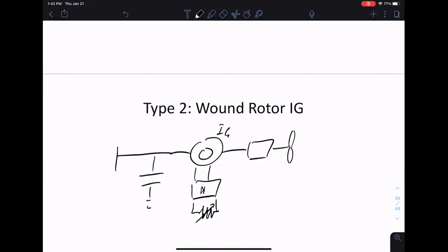Sometimes if the wind is blowing, for example, at too high of a speed, and you want to slow down the turbine, you want to control the speed. One way to do it is just to burn the power through a load. And this type 2 attaches a variable resistor to the generator to get rid of this load. So if one blows at too high a speed, this is the way to dump power. Any questions about this, at least in a conceptual idea?